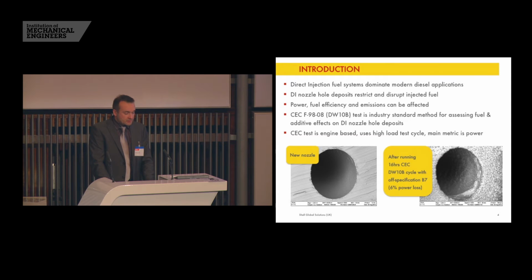So there's an industry standard test for evaluating DI nozzle hole deposits, and this is developed under the auspices of CEC. It's commonly known as the DW10B test, and its focus is to evaluate fuel and additive effects on DI nozzle hole deposits. So the CEC test is engine based. It uses very high loads, and the main metric is power.